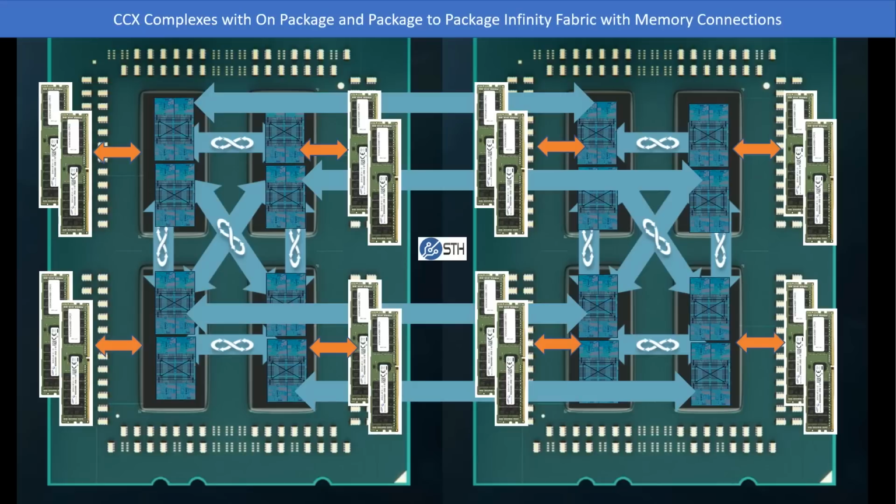Now, most of the tech talks that you'll hear and one of the slides that we saw earlier depict memory hanging off of this Infinity Fabric. And what you'll see is that each of these dies has 2 memory channels. And so you can then trace the Infinity Fabric. So if a level 3 cache or level 2 cache needs some data out of RAM, you can traverse the appropriate Infinity Fabric and go get that data, and you can trace how that would work if there's a 1-hop or a 2-hop to get there.